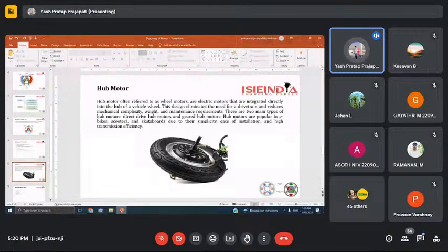This circuit switches the power on and off in the coils, in turn creating forces in each one that make the motor spin. Since the brushes press against the axle of a normal motor, they introduce friction, slow it down, make a certain amount of noise, and waste energy. That's why brushless motors are often more efficient, especially at low speeds.